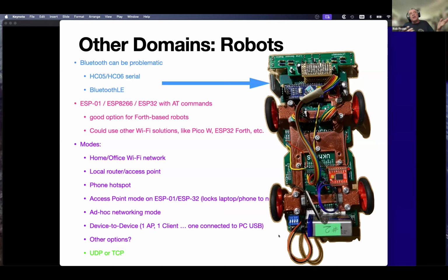So there's some advantages, right? Wi-Fi's got a load of bandwidth. You can obviously operate multiple sessions at the same time. You can have a logging session, and you can also have a terminal interaction, or more than one terminal interaction session, without doing the multiplexing you'd require on the serial interfaces.